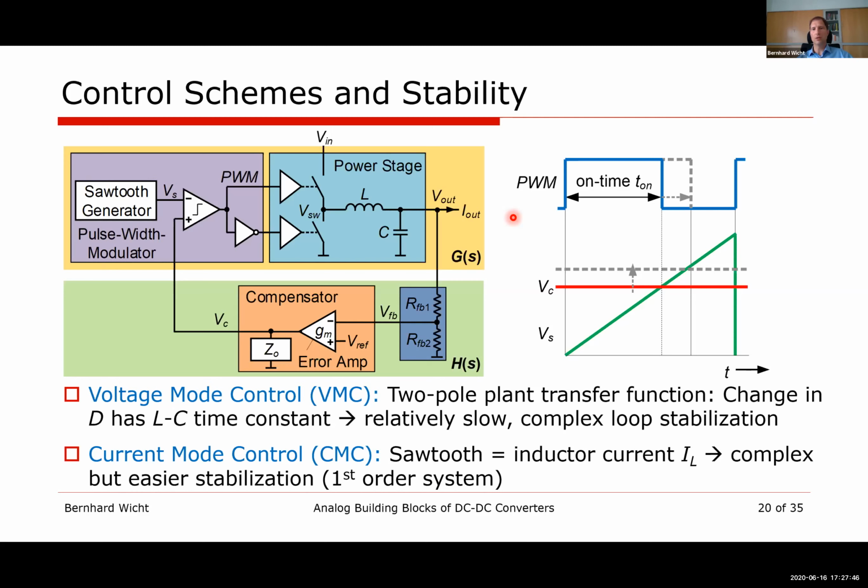And of course, we know the voltage drop across the linear regulator is losses, and we want to get these losses to a minimum. So typically you have a voltage drop across the linear regulator of a few hundred millivolts, like 300, 400 millivolts, right? Okay. Sure.